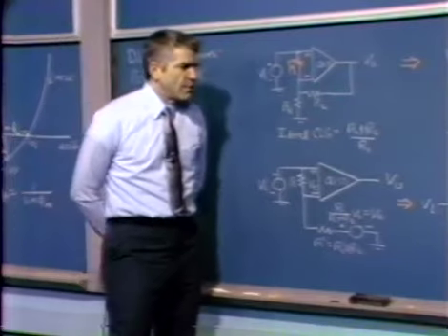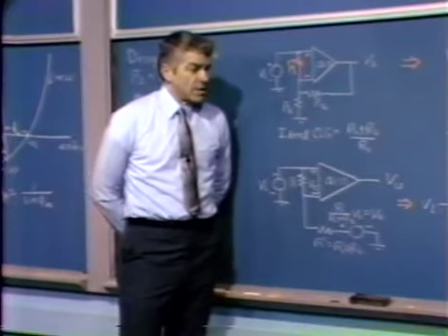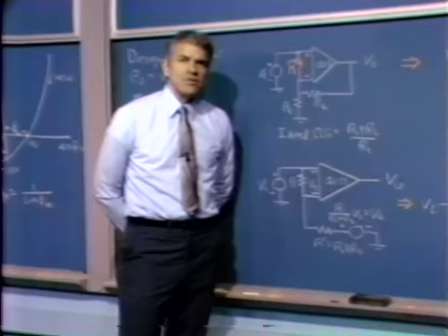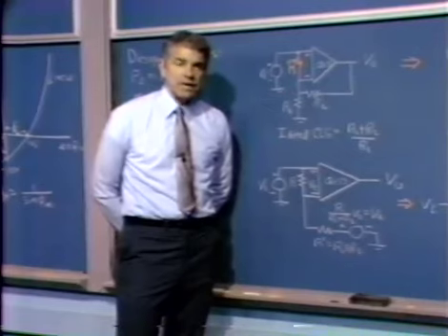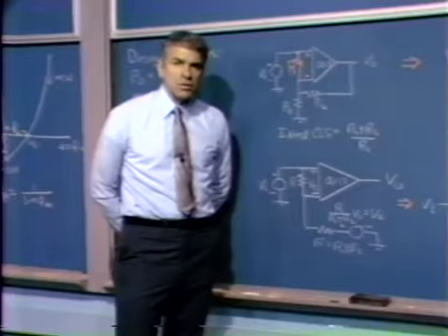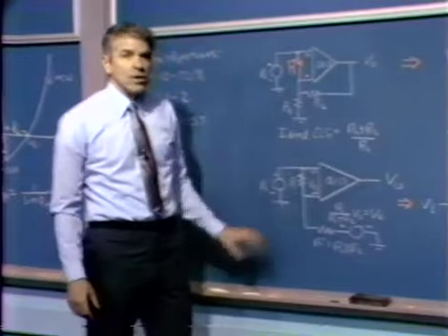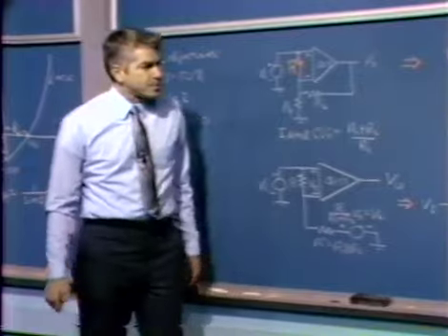As I say, there are commercially available amplifiers that are intended to run that way. You gain certain advantages in the design of the amplifier if you design it other than for stability with direct feedback. And when that happens, if you want to run the amplifier at low closed-loop gains, this sort of an approach allows you to maintain stability.